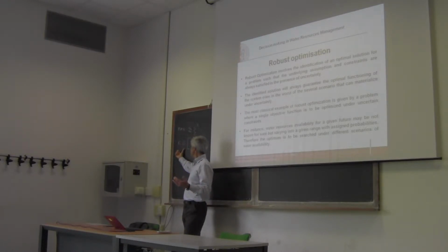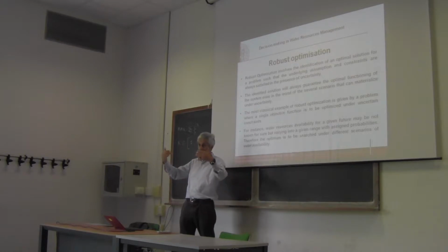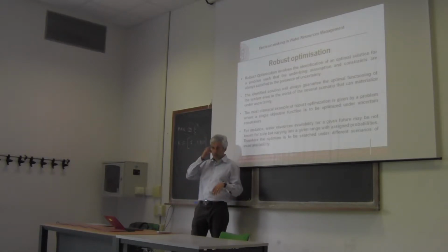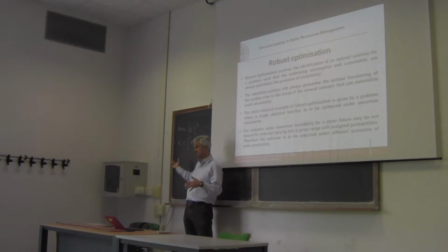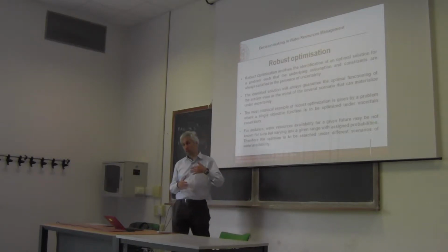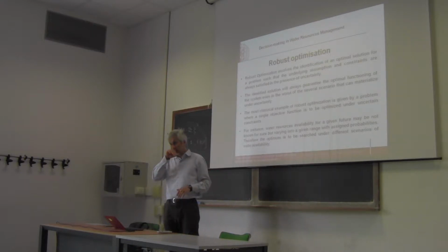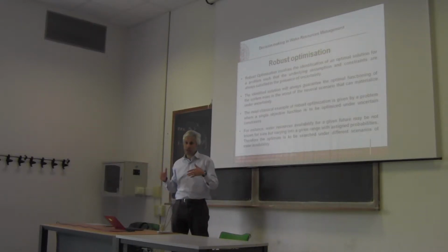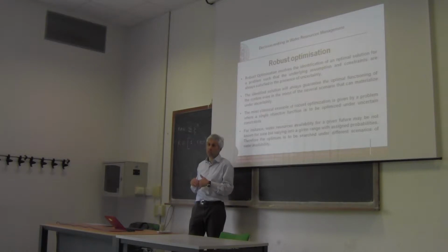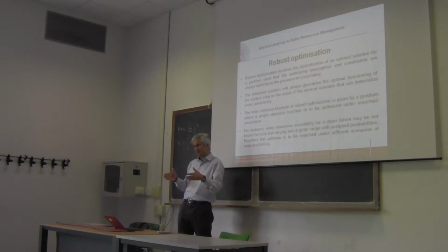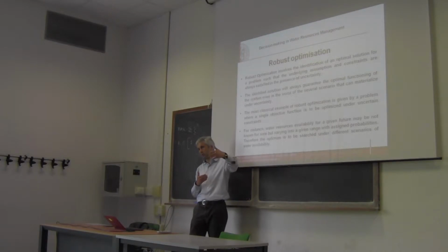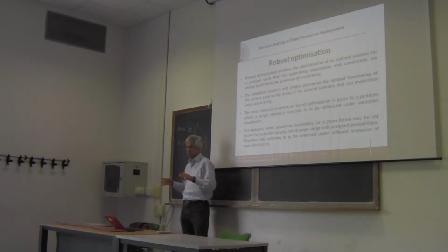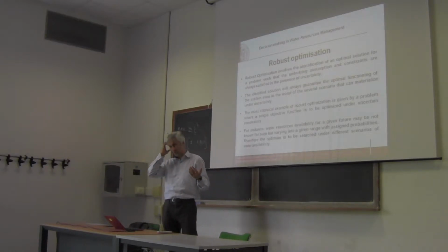It's something that is a range for the parameter that helps the program to find the optimum. But we didn't put any constraint. Usually, in optimization, we are also allowed to put constraints, which means that, for instance, we may want that there is a minimum flow that is left into the river when we design a water withdrawal. We made this example. And this minimum flow, it's environmental flow, it's a constraint.